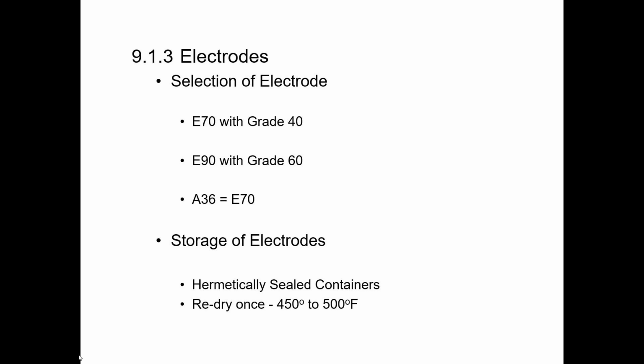So for the sake of this book, it really should have been specific to a lap weld connection, and for anywhere that electrodes are mentioned in that paragraph, it should read E70, assuming that it's for a lap connection. You might make a footnote that those changes are assuming a lap connection. So hopefully that's not confusing for you. Hopefully that makes sense.